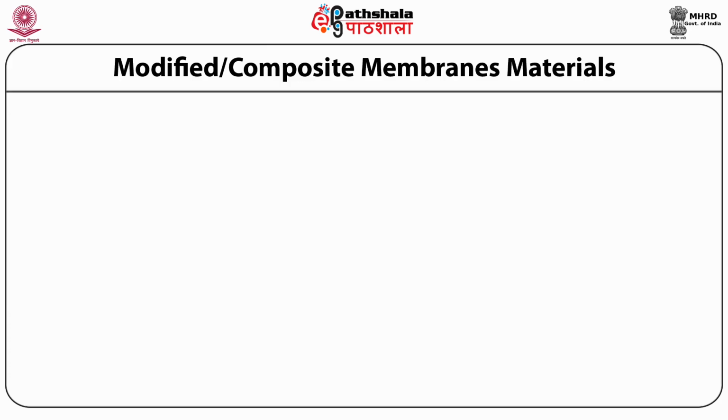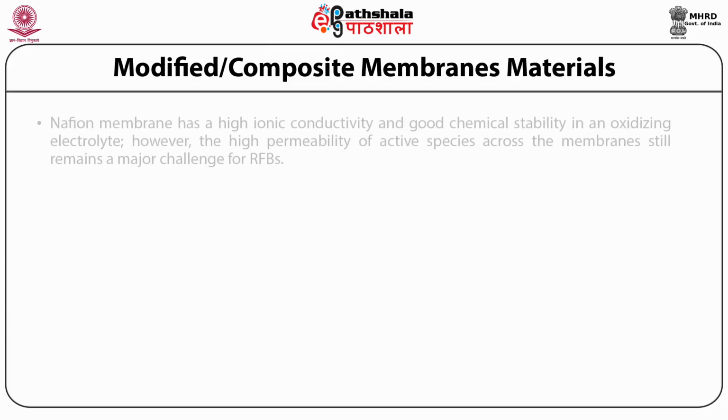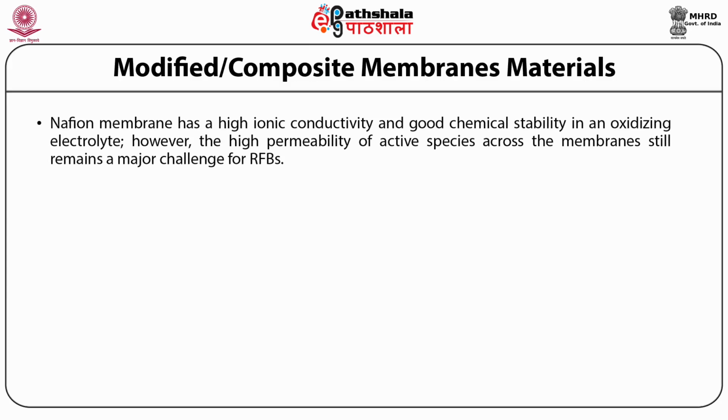As we have already discussed, Nafion membrane has a high ionic conductivity and good chemical stability in an oxidizing electrolyte. However, the high permeability of active species across the membranes still remains a major challenge for RFBs.